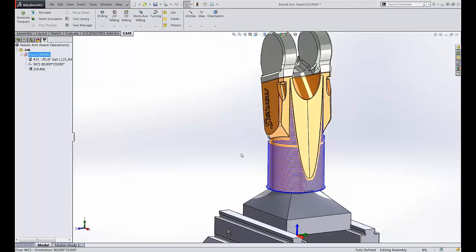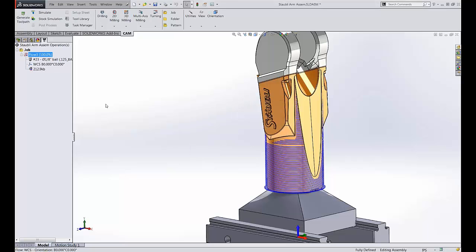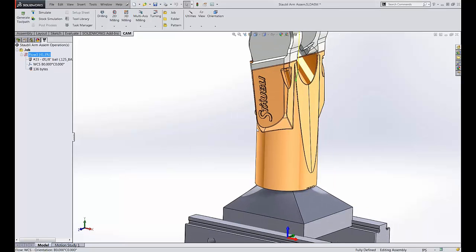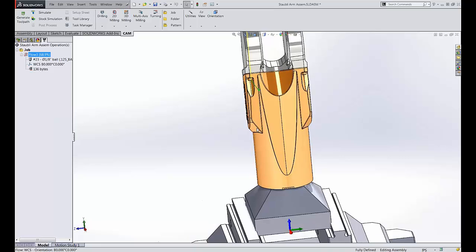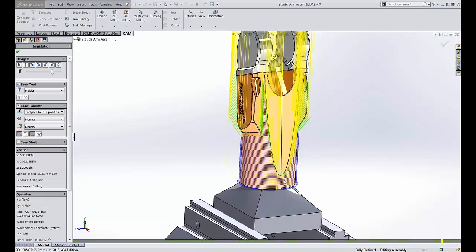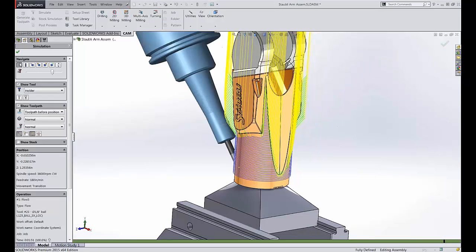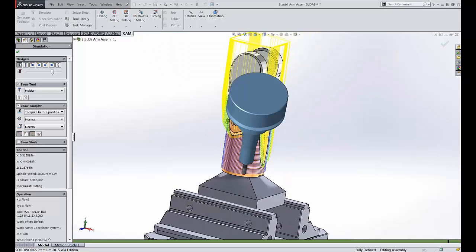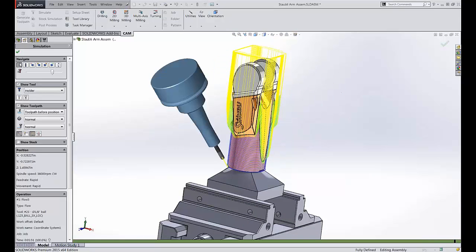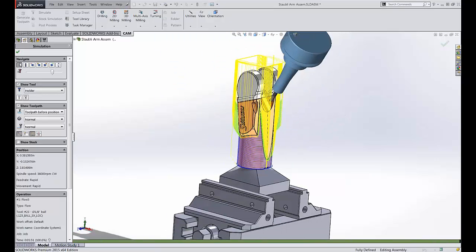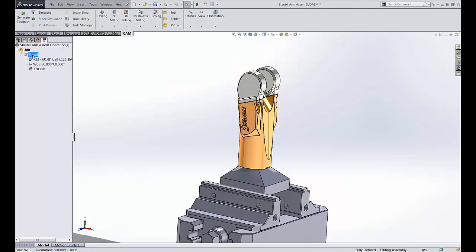We're 99%. Yeah, I think it's important to note, this part you've already said, but it's a really good candidate for a lot of 3+2 and then a handful of true 5-axis toolpaths. We got a buddy that worked at a major auto manufacturer, and he had access to everything you could dream of, and often he said, in the end, he often got better surface finishes, programmed faster, made parts faster with 3+2 machining. This is a perfect example of when you would want to go to a flow 5-axis toolpath.